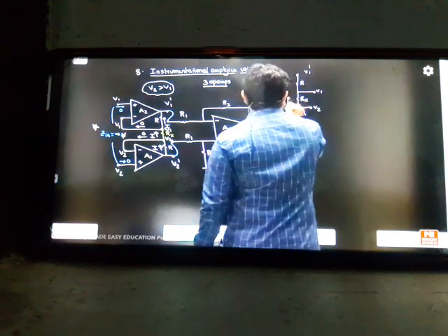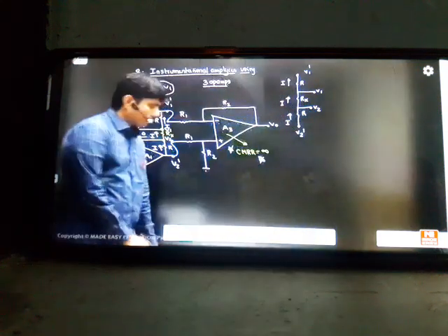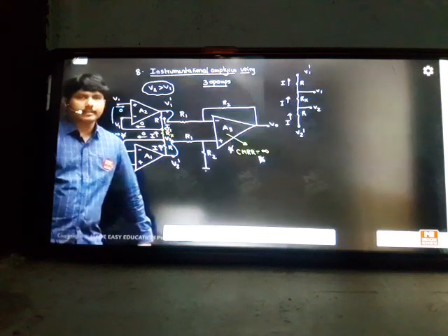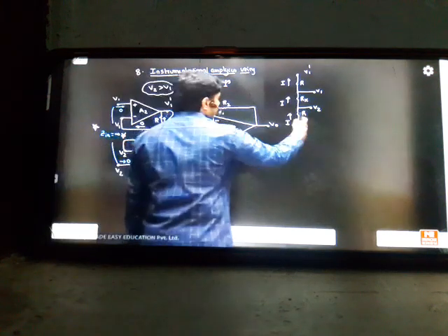Same current I is going. So this is the situation. Because of the current drawn in the circuit, these 2 drops are not the same. Your virtual short point and your V2 dash will be different because R is there in the middle of the circuit. Let us find out these 2 answers. What is V2 dash and what is V1 dash?